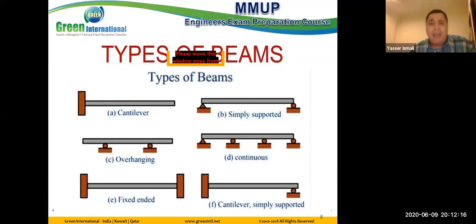Once I get the internal forces, I will get all the internal stresses. From these stresses, I will check whether the section will stand the external force or not. I'm going to design the section, the size of the section, the area of steel, and what type of concrete or steel is suitable for our design.